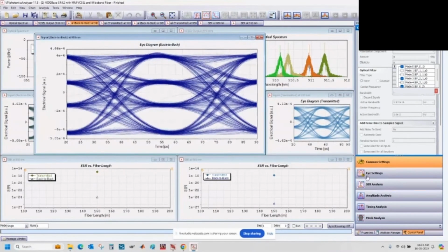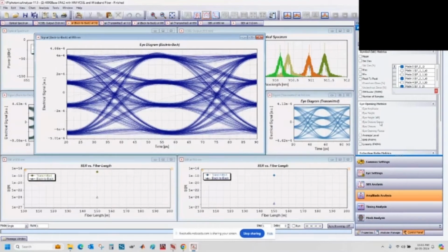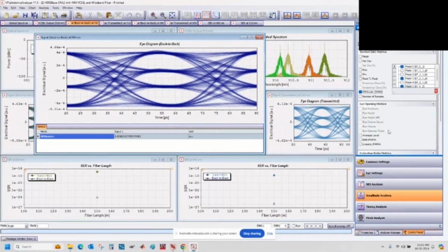And we see for the eye diagram, you can just refer to the requirements, to the specifications in the standard. We can analyze this eye diagram and look at metrics such as the optical modulation amplitude, for example. You can look at that directly here. Also the eye height for the different eye openings, and this also means the different levels of the PAM signal.